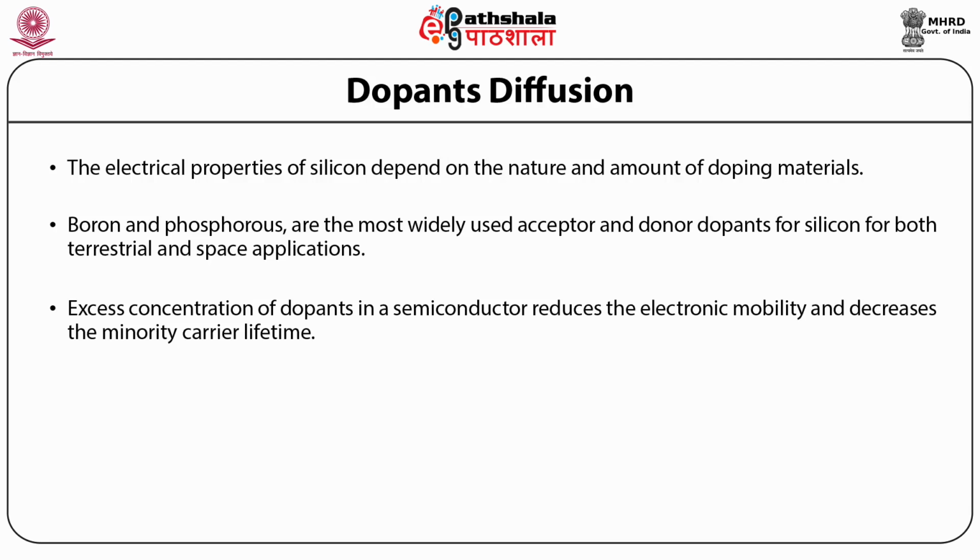Then the N layer on the p-type semiconductor can be obtained by diffusing a donor concentration into the p-doped semiconductor layer, exceeding the density of acceptors, thereby growing an additional N-doped layer. This N-doping in a semiconductor is achieved in several ways. Generally, the p-n junction is made by the diffusion of dopants.